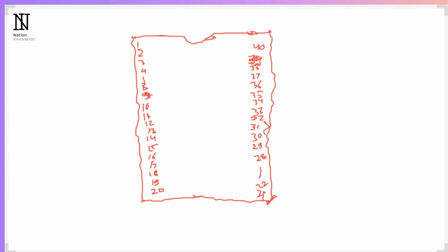So we were discussing 8051 architecture. Today we are going to discuss the 8051 pin diagram. I have drawn a rough sketch for understanding. So 8051 is a 40 pin IC. From the notch, we start from 1 to 20 here downwards, then from 21 to 40 upwards in this direction. Now let us see what basically each pin stands for.